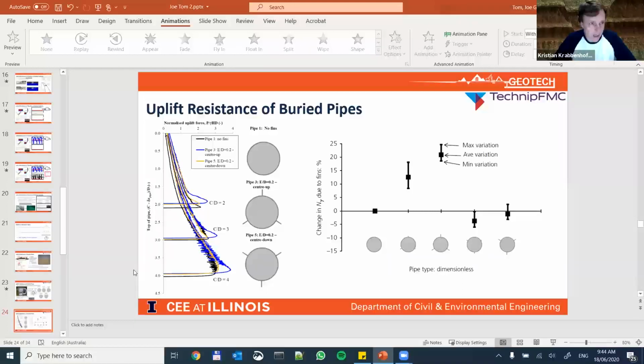And what we've done as well is calibrate this model to a large database of sands from NGI, so that you are actually able to enter a relative density and then internally a stress level dependent friction angle will be calculated automatically. All the equations and everything is in the manual. So that might be something to consider. Yeah.